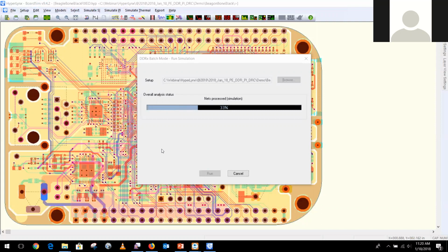Again, it's not because you want everything, but the earlier you catch design issues, the less pain you will have to go through, and it costs you more later. That's a 10x factor when you're jumping from pre to post. And if you don't do simulation in post and you go through manufacturing and into the field, that's another 10x factor if something fails in the field. So it is advisable to check things out in pre-layout.